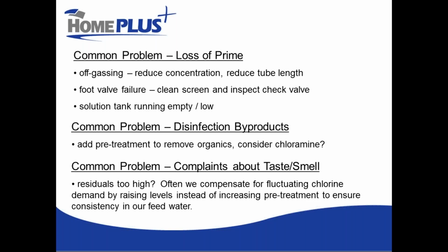If you're having problems with disinfection byproduct formation, most of the time what you're going to have to do to solve this problem is look at removing the organic precursors. So you're going to be pre-treating to remove the organics. That would be beneficial to taste and odor, for UV dose, and for chlorine consistency, and it would eliminate the disinfection byproduct formation. Granted, removing organics is not always easy or practical in a lot of small systems,